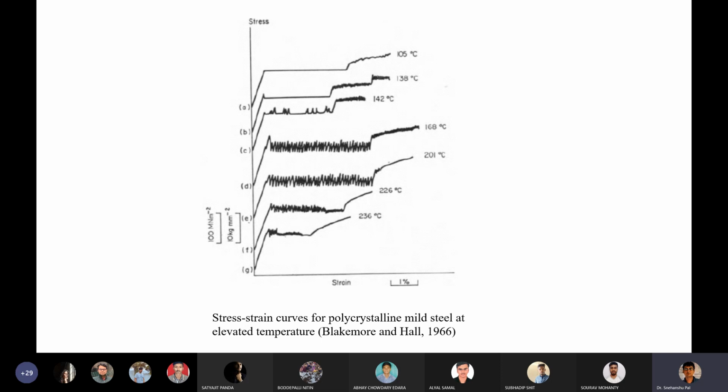So after a certain time, strain hardening enhances the yield point, and after that UTS is reached, and then it is not going to carry the load; it is going to fracture. This is the scenario. Still, in this area, the yield point phenomena and serration from material to material, the underlying mechanism is not clear cut. Some interstitial atom and defect interaction for mild steel, people used to argue, but it is still not so clear. So it requires a lot of study and research.